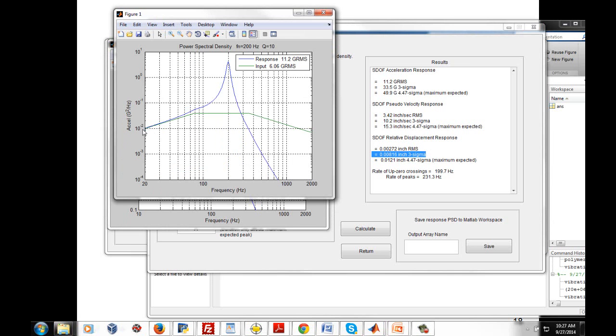If we go to figure 1, this is our NavMat base input. By the way, this is a power spectral density plot, G squared per hertz versus frequency in hertz. And this plateau here does have a level of 0.04 G squared per hertz. But what if our natural frequency fell on this ramp here or this downward slope here? In that case, Miles' equation would start to give us some error. How much error? Well, you can do your own numerical experiments.